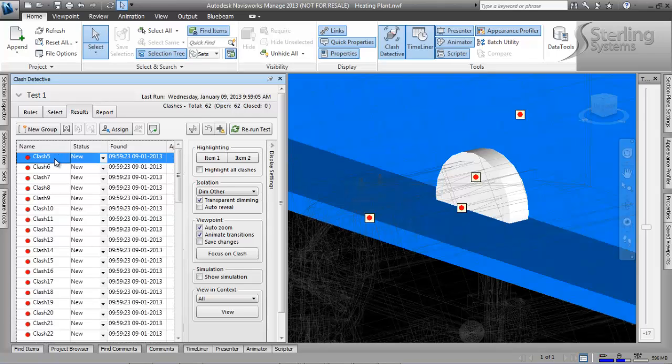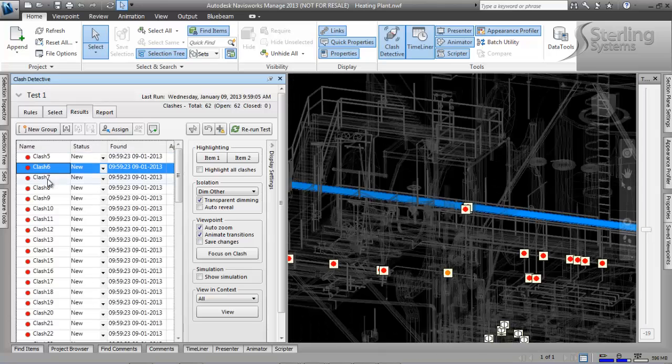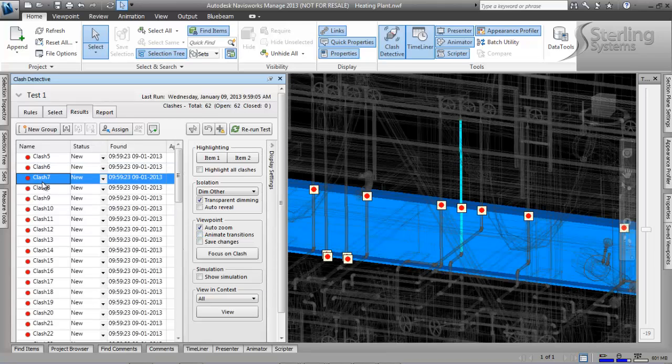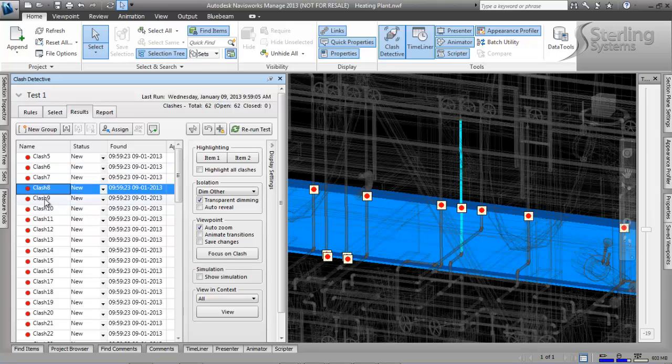And what this does is it pulls all the clashes together within the view. It's going to send me to each one separately. Sometimes you have to rotate around to get that. And you have several different features over here on the right that help you. I'm going to take off animate transitions because I don't want that going through, and I can automatically go to it very quickly. Now take this and run through it, add your comments to it.